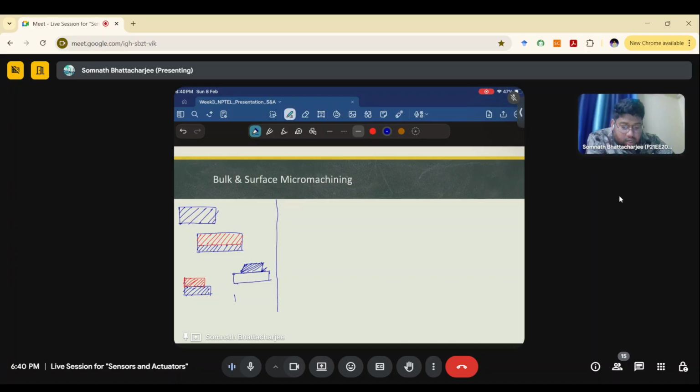But when you are trying to deposit PR, you are spin coating on top of it, and then you are baking it as well. So even if there is any kind of air bubble, that will get removed with these baking processes. And you are doing some pre-cleaning as well, so there won't be any debris or contaminants that will create a layer in between the PR and everything. So your PR and your device will be completely adjacent to each other.